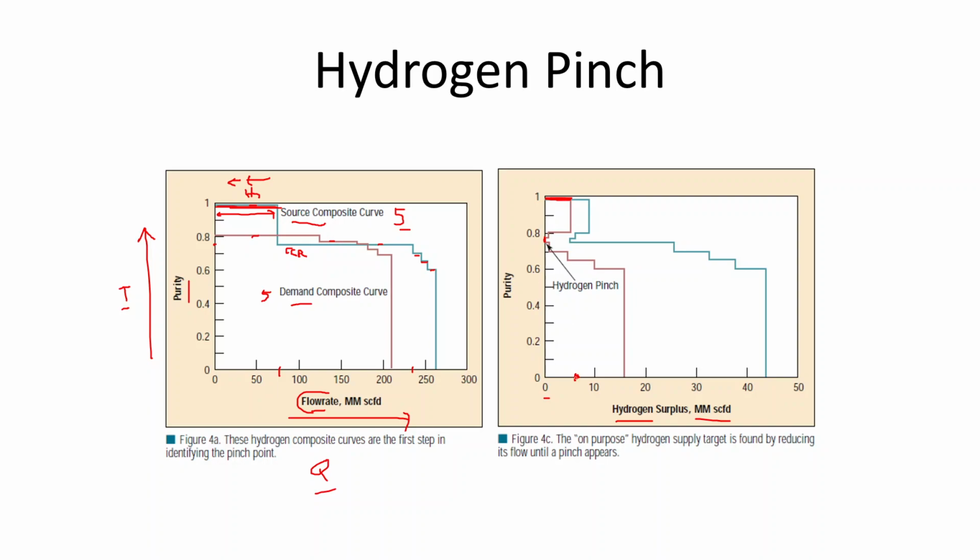So if someone tells you, from your plant data, that they have this technology or whatnot, and they say, well, we can calculate this and build for you, and the hydrogen capacity would be like 5, so it's a lot less than what you previously have, and you know how to calculate this, then you can tell that they are lying or bragging. Because thermodynamically, in this case, it's a mass balance case.